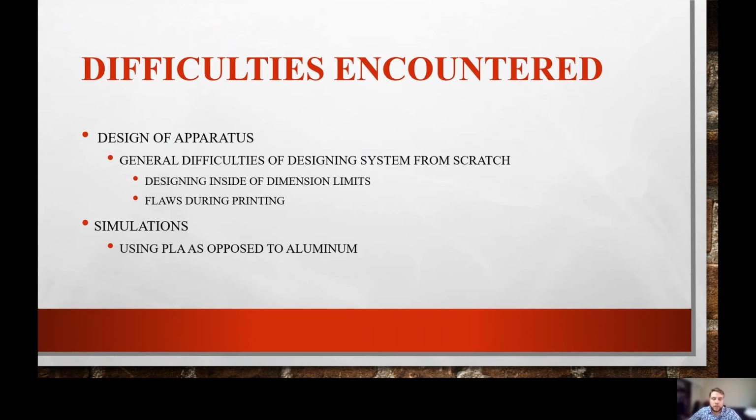But also, because the modulus is so low, we would hit some of the natural frequencies of the PLA during our testing, and it would excite the PLA, which would throw feedback noise into our test results, which would give us nonlinear responses, and we couldn't use that data. That is the big issue that we came into when we were doing the hammer testing for the clamped free configuration.